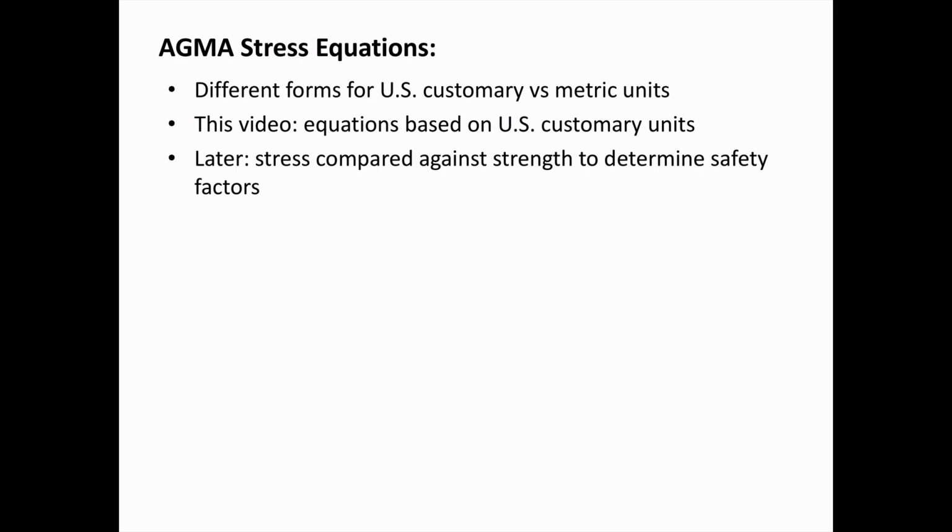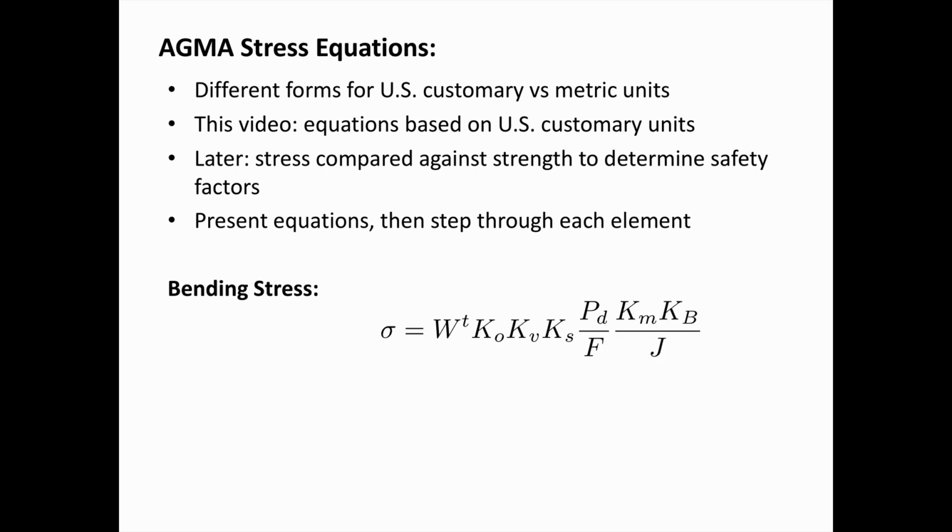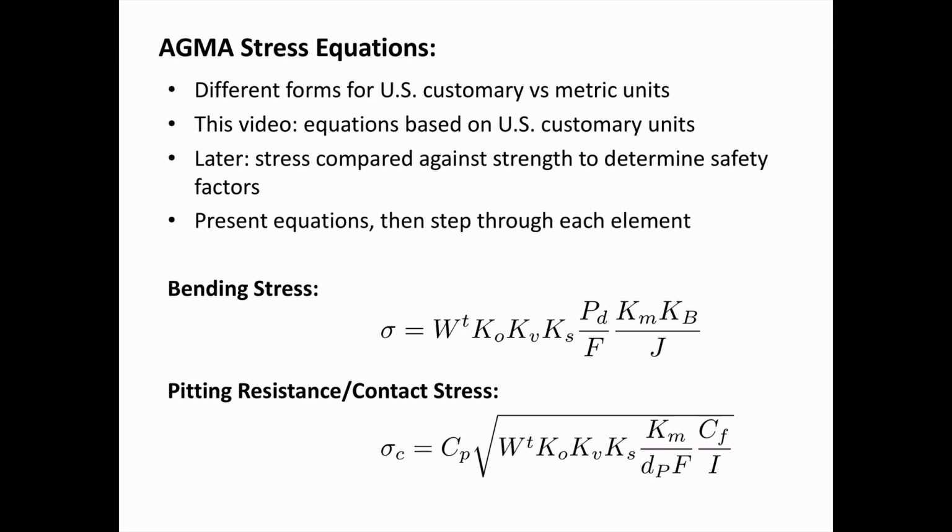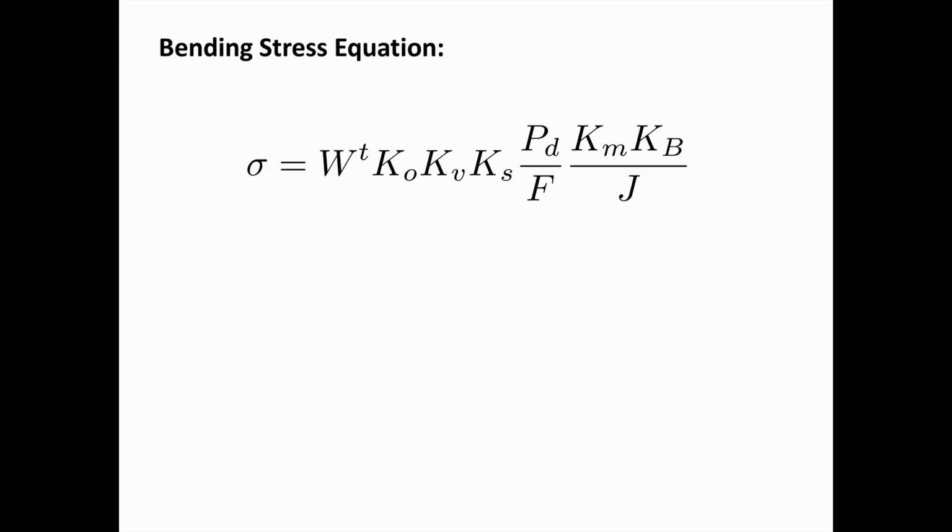Later, we're going to compare stress against strength to determine safety factors. I'm going to present the equations, and then I'm going to step through each element in turn. So here's the bending stress equation, and then here is the contact stress equation that we need for predicting whether pitting is going to occur.